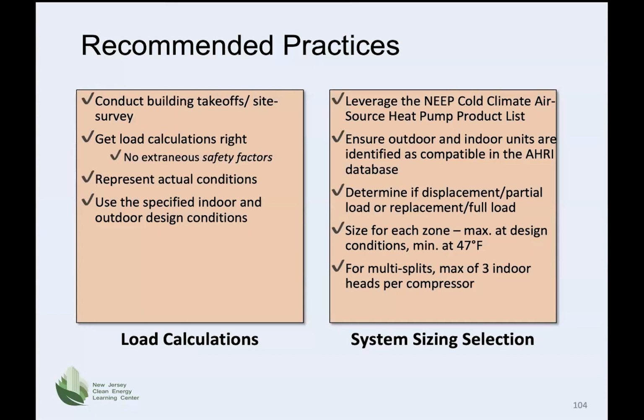First, you want to use the NEEP database that lists cold climate air source heat pumps as well as different manufacturers' data. And then you want to ensure that the outdoor and indoor units are identified as compatible with the Air Conditioning, Heating, and Refrigeration Institute database. In other words, your outdoor unit, and there are different options for the indoor unit, but those two must be paired and identified within the AHRI database as being compatible.